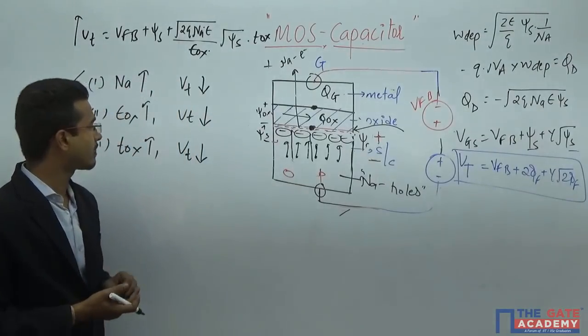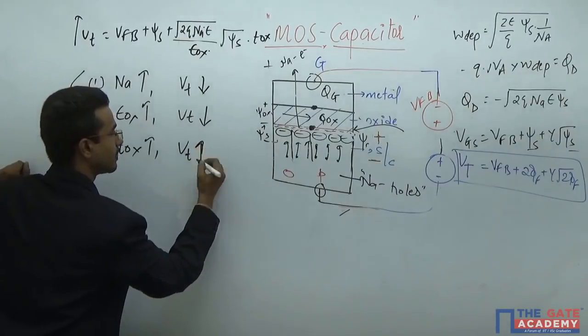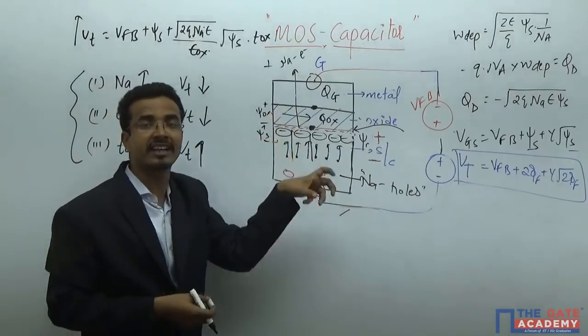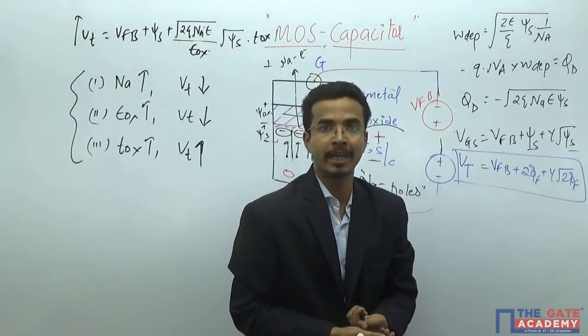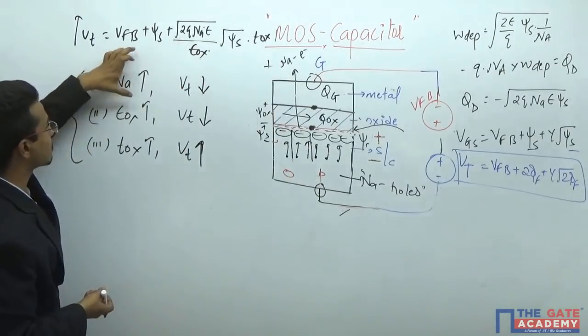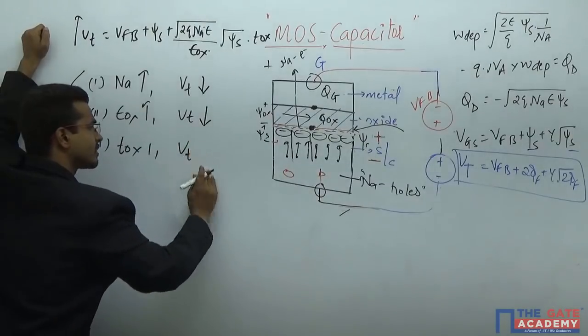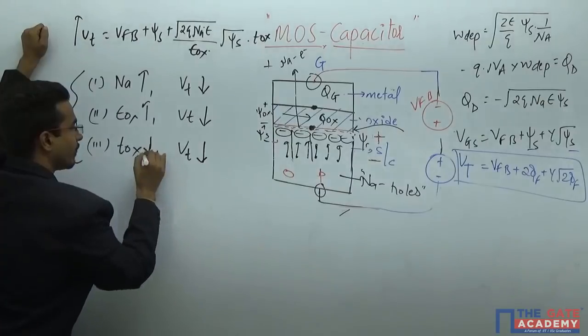And all the time you will try to reduce the value. All the time you want less voltage required to generate the opposite drive or charge carriers. So your interest should always be to decrease the value of the VT as much as possible. So to decrease this VT, what is required? You will decrease the value of the TOX.